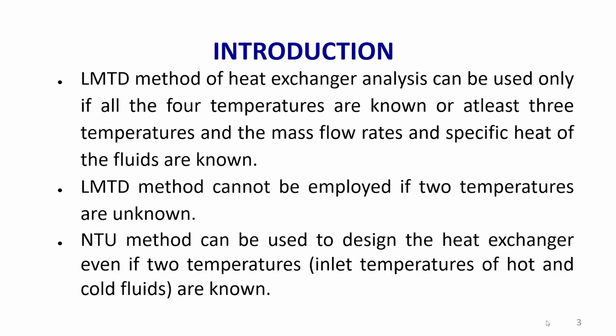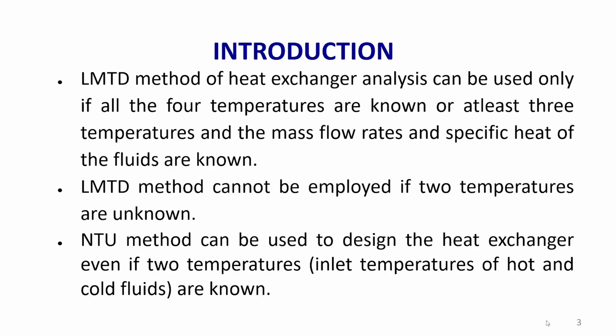So, the LMTD method cannot be employed if two temperatures are unknown. Suppose the inlet temperature of the hot fluid, capital T1, and the inlet temperature of the cold fluid, small t1, are given. Then we will not be able to find the value of Q, using the basic relation m Cp delta T. So, there is a limitation on employing this method if we do not know all the temperatures.